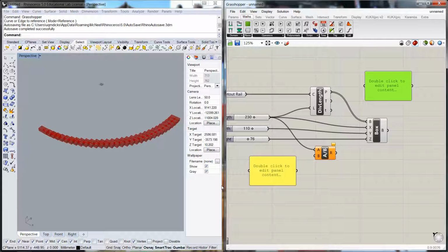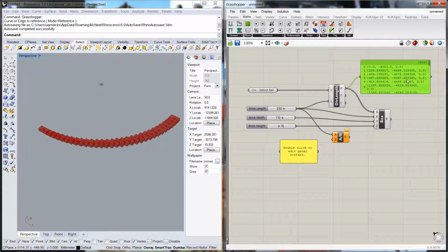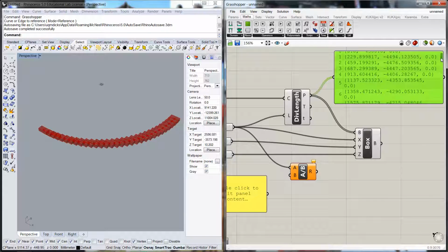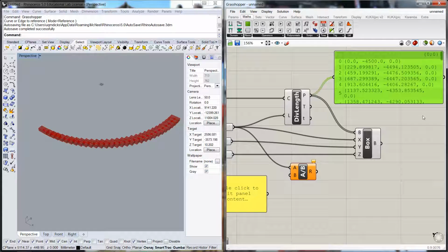I've just copied this panel, and for example, if I wanted to see what was actually coming out of that parameter, you can see here that we can see this as a list. It's showing us all of the data coming out of that as a series of X, Y, and Z coordinates. Sometimes that's useful in reverse engineering someone else's Grasshopper routines, because if you're not sure what the parameter is actually doing, looking at what the output is makes it a little easier to understand.